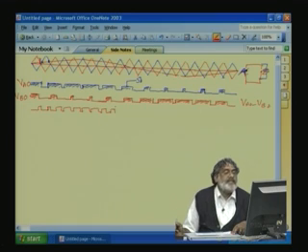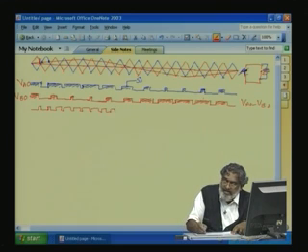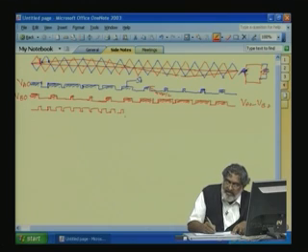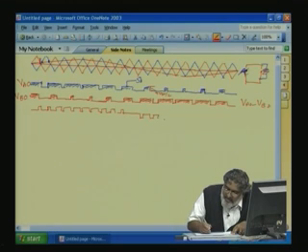Here it is VDC by 2, and this height is also VDC by 2, but in this case it is VDC, because for subtraction, minus minus gets added. To fit the whole waveform within the page, I have slightly scaled down the height, but the actual height is VDC here. That is the VAB waveform.